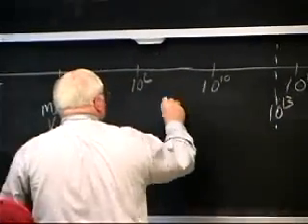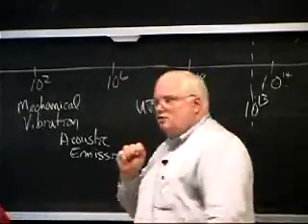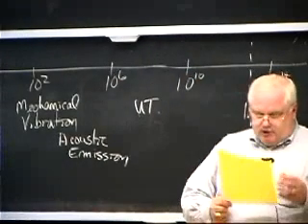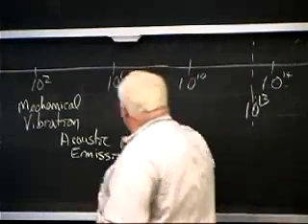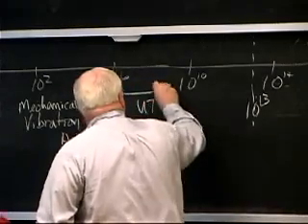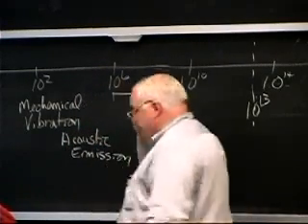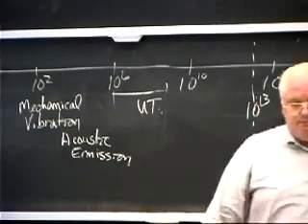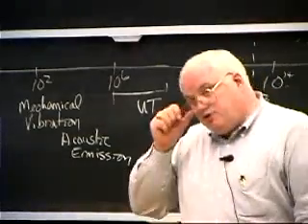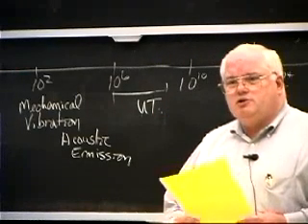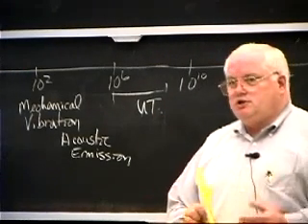Ultrasonics. Ultrasonic testing is in here where you use a transducer typically at anywhere from 1 million to 10 to the 8th hertz. Most of them at 1,000,000 hertz, you're typically looking at flaws 2 or 3 millimeters in size. Well, 3 millimeters is 1/8 of an inch, right?